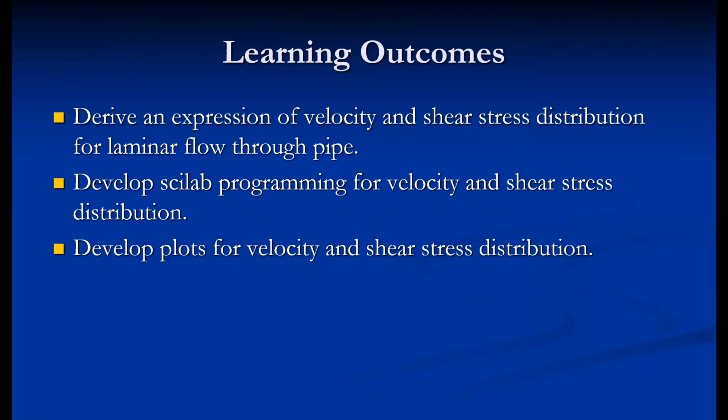It's a small experiment, but we should understand how to write the program for a simple analysis of flow through a pipe. So here initially we refreshed the derivation of velocity and shear stress distribution for laminar flow through the pipe. Then we studied how to develop the program for velocity and shear stress distribution, and finally developed a plot of velocity and shear stress using the plot command.